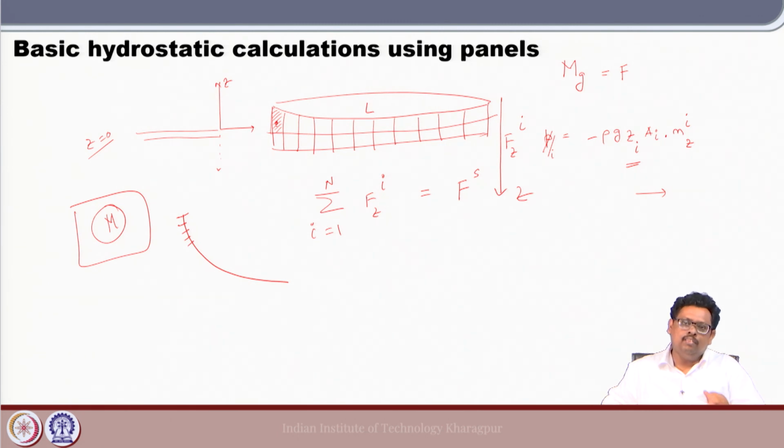So normally what we do is we make a little compromise on the paneling. At the end we are replacing this geometry by a number of sources. That is the essence of the boundary element method. So we really don't want that rigorous paneling, because the panels are only important for the geometric calculation, like areas, since each source is associated with an area.